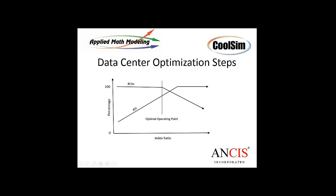And so before I can get to 100% of RTI, before I can get to an even amount supplied equal to the amount required, I start to run into hot spots. And that's exactly what that is showing as it rolls off. So our goal in this next example is to find this point and then push it to the right by doing air management techniques, and therefore get RTI as high as we can and RCI high as we can. This will by nature, by definition, take care of RCI low